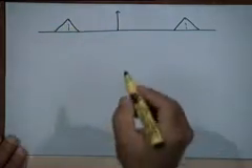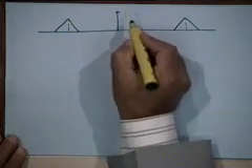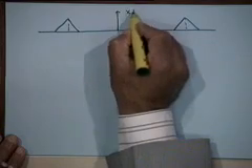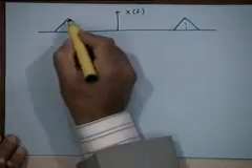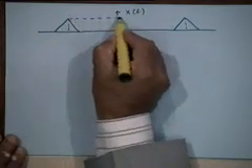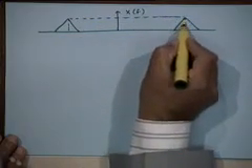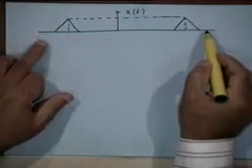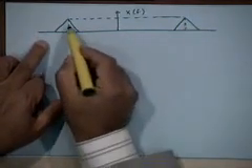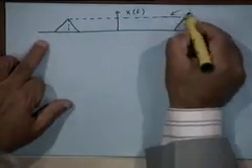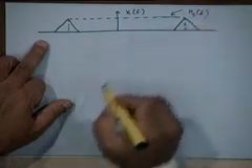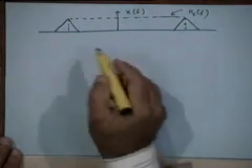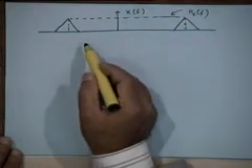As we know, we can generate an SSB signal by starting with a DSB-SC signal and then low pass filtering it. So I must multiply the message spectrum, which looks like this, with, let's say, the transfer function of an ideal low pass filter which looks like this, and that will give me the lower sideband signal.